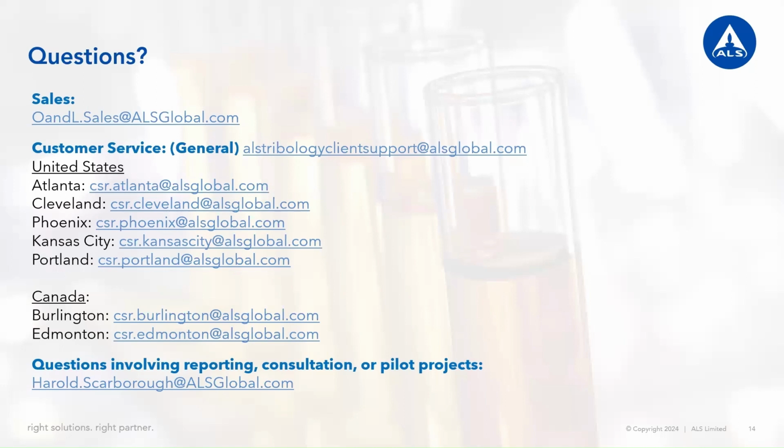Is oxidation used more than TBN now to determine oil life? That is something that is occurring more often. In the past, TBN has been pretty much the gold standard for determining how much life is left on an oil. This has slowly been changing over the years. TBN is a test that is a little more prone to human error, and slight variations can mess with the value.